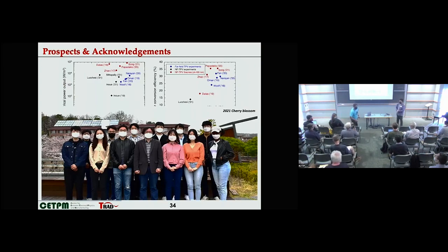Yeah, I have a question about the efficiency. You defined the efficiency as the ratio between the heat and the work given to the system, right? But this is the efficiency based on the first law. There is an efficiency based on the second law, which considers the dissipation more accurately, right? And this second-law efficiency is smaller, normally much smaller than the other one. Perhaps it could be interesting to see.